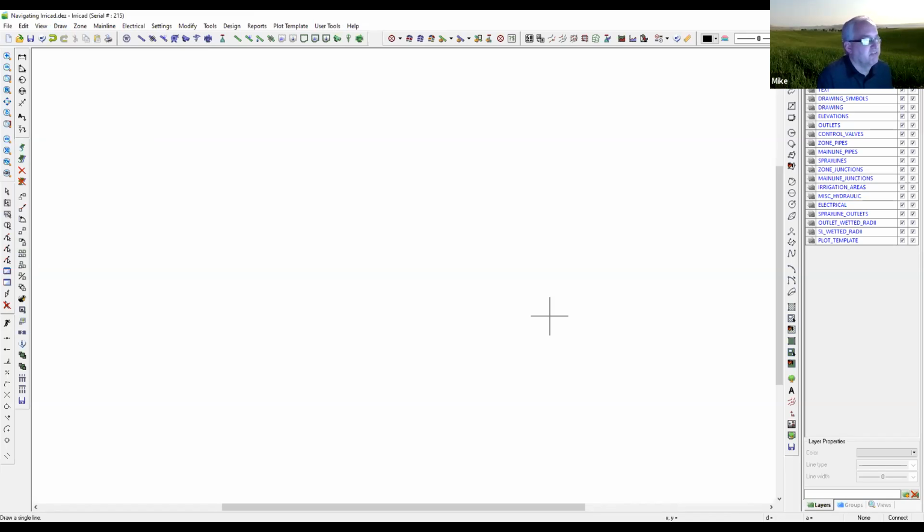If I go here and I've started a line, down here in the lower left-hand corner, it's going to tell me it's waiting for me to draw a line. I'm in the single line mode. There's a couple different ways I can do that. Obviously, I can just left click on my mouse to start a line. I'll have this green rubber band attached to my cursor as I pull towards wherever I want the second point on the line to be. And if I just simply left click, then I've drawn my single line.